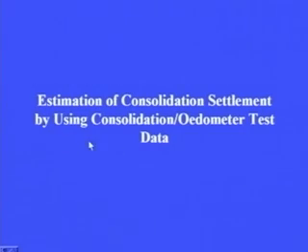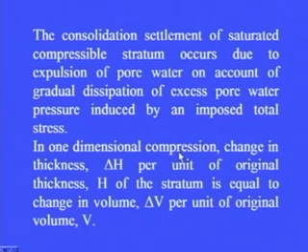Estimation of consolidation settlement by using consolidation or oedometer test data. The consolidation settlement of saturated compressible stratum occurs due to expulsion of pore water on account of gradual dissipation of excess pore water pressure induced by an imposed total stress.